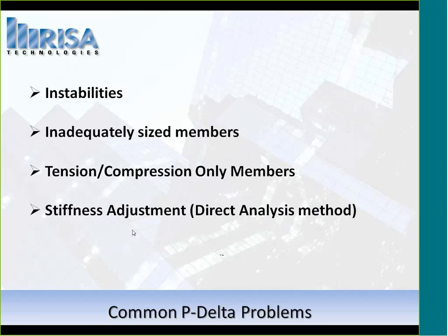If you can get past it, then maybe we start to look at why the stiffness adjustment is causing it, and if it really truly is a lateral member. Sometimes folks send their models into us, and they don't realize that lateral is the default, and so maybe they can switch a couple of members to gravity and get past that. So you've got that, and then model errors.